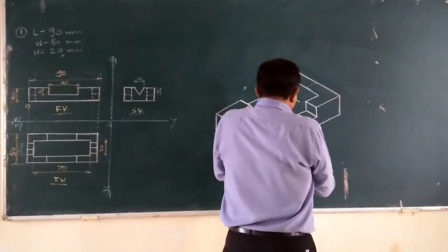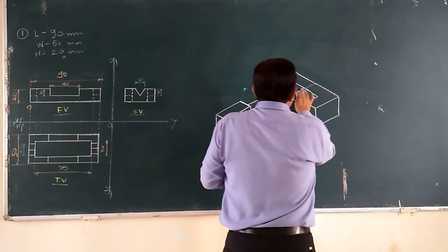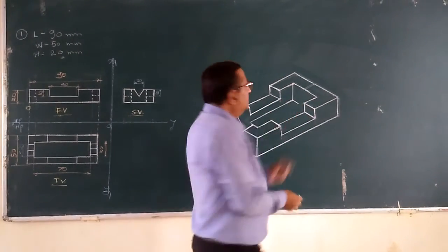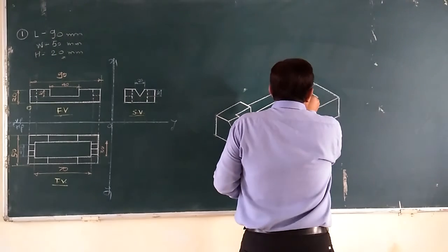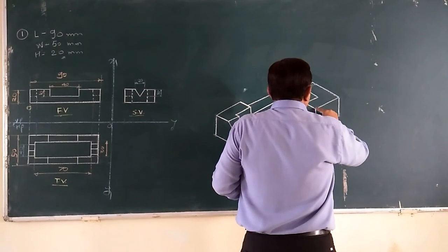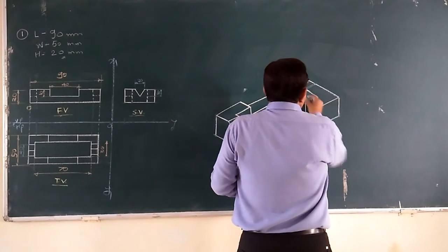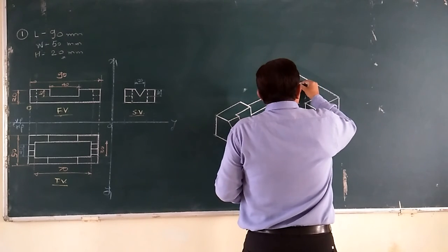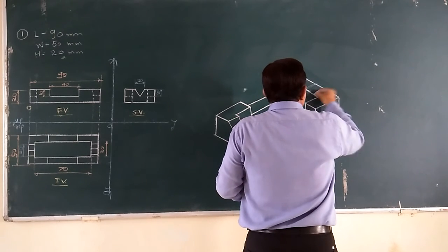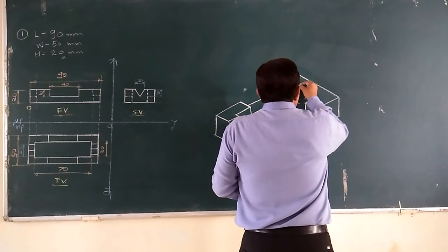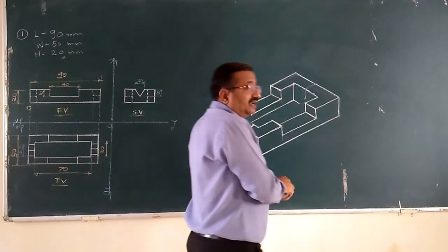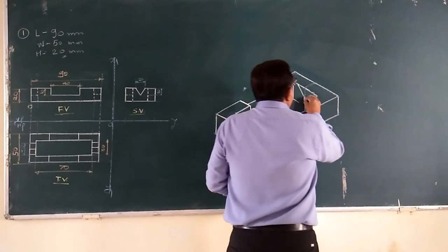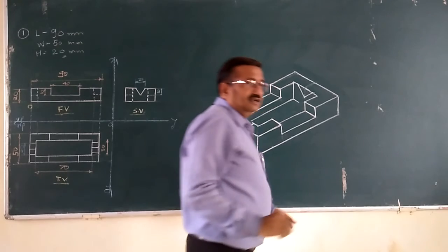Now I have drawn the center line. From this, on this wall, on the inner side only, such kind of V slot will be visible. So naturally you have to stretch one vertical line here. Again the same trick, 10 mm depth you have to mark here. 10 mm left, 10 mm right. Again those points you have to locate. Okay. Yes, of that V notch. First of all I will connect. I will sketch that V notch.